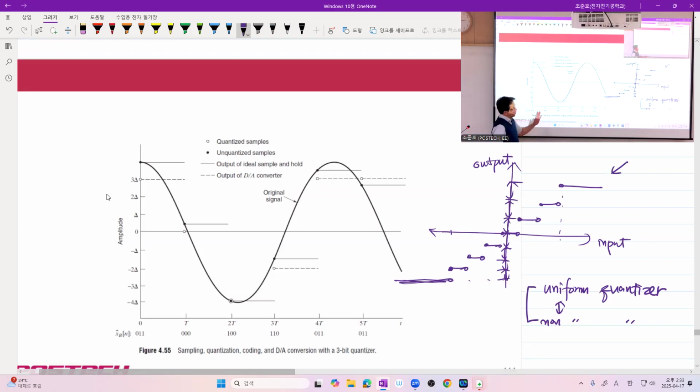And the second one is that some implementations of quantizers are not this way. What does that mean? This is actually the so-called clipping quantizer. So if it goes over some range, then the output is saturated. But it's not always true. Some have a very interesting thing. It's repeating here, up to some points. Not infinity, but. Got it? Some quantizers have a strange thing. If the input value goes over some range, it's 0. So depending on how you build your A to D quantizer, your mapping curve may differ a lot. Okay? So you have to have an open mind.